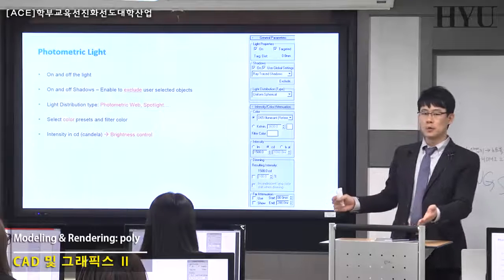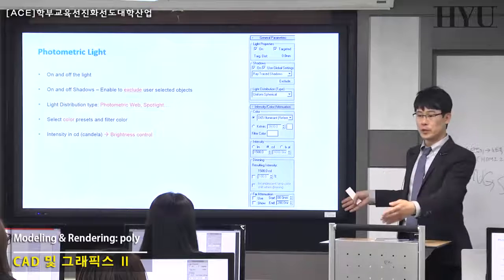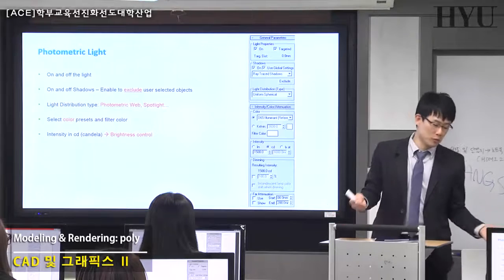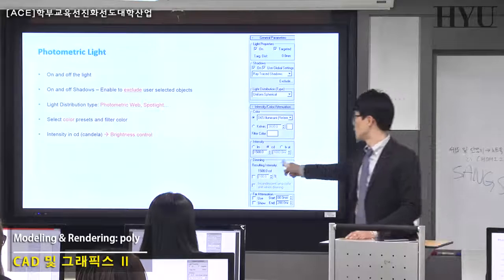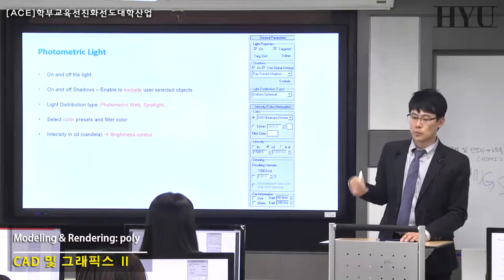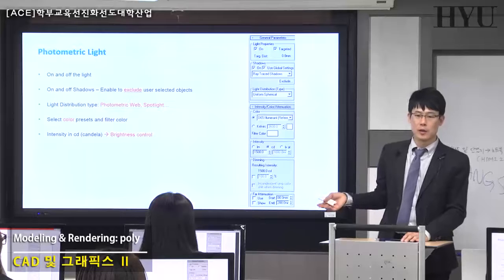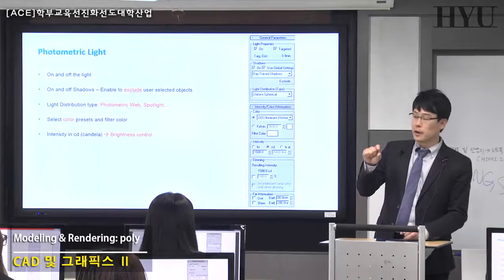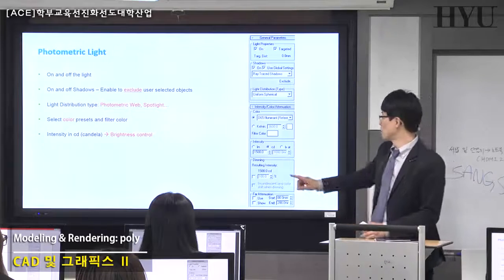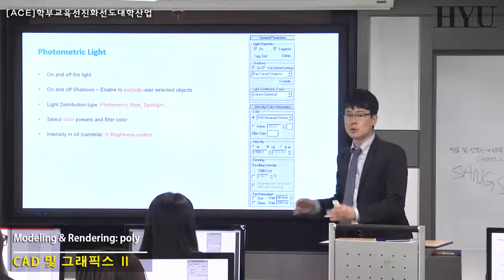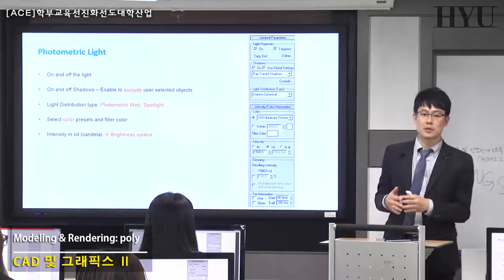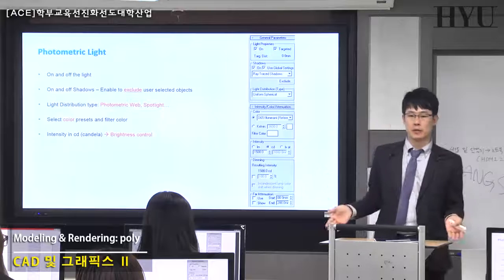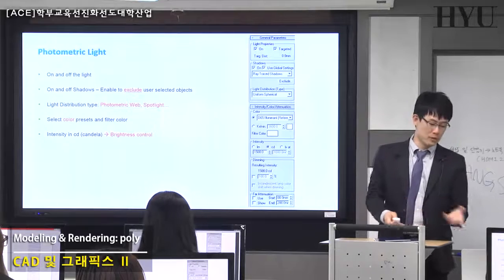Another one, if you model 1 kilometer by 1 kilometer huge box building without intention, this kind of light shows nothing, okay? It's up to the scale. If you are modeling very tiny object and this light, same number, but totally different brightness because of its scale, okay? You have to follow human scale when you are designing your object in 3D Max.